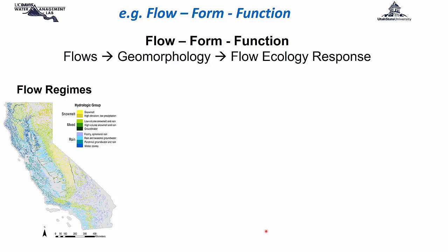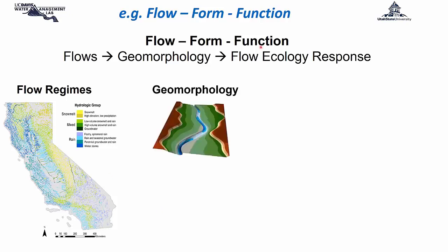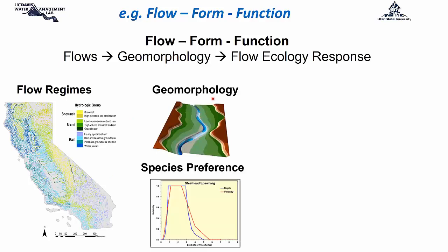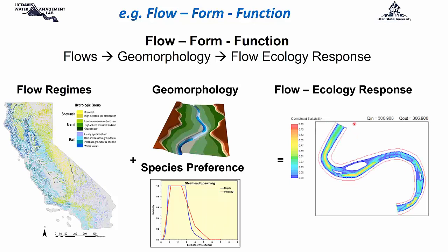That is related to how to relate flows to specific channel types and geomorphology, so that you can put certain preferential curves, certain functions, and estimate when you can generate improved habitat or when you're not going to have that much habitat. So the red will be good habitat suitability and the blue one will be low habitat suitability. And this is what I was talking to you about. So you have a range of velocities, and given the range of velocities throughout the riparian corridor and these preferential curves at a given flow, you can actually estimate where you're providing good habitat or not.